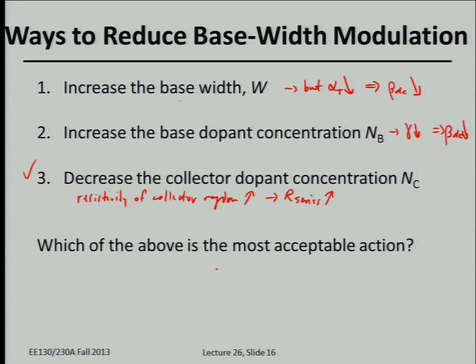That's the reason why, and I think we'll cover it next time, in a modern BJT we actually have N plus contacts here. We have heavily doped regions down here, the so-called sub-collector, just to reduce the series resistance effect. So you have the emitter, the N-type base, and the P-type collector in this case. People make structures like this just to mitigate the series resistance problem.